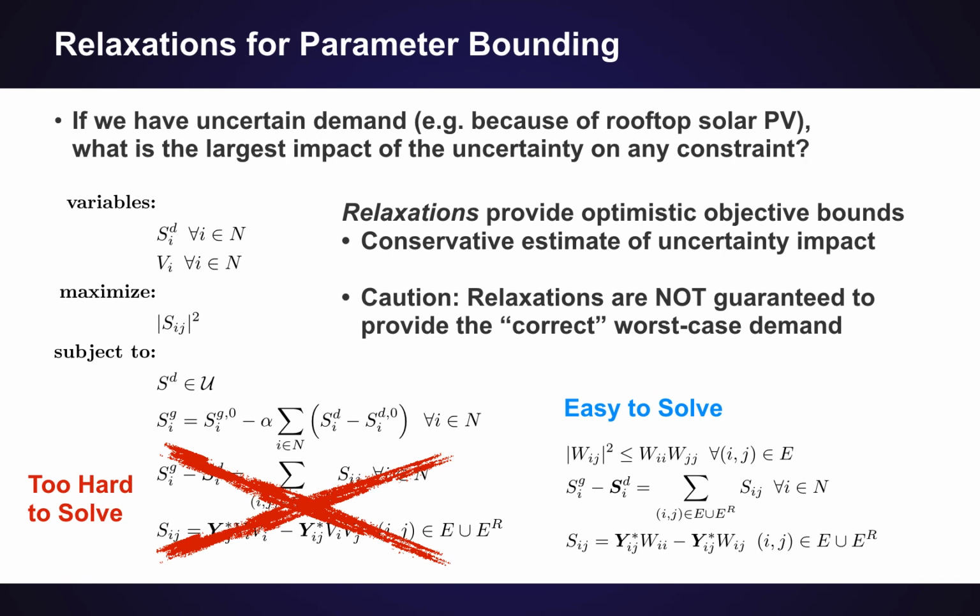Also one thing I would like to note when we are looking at this problem is that here is one good example of a case where we are changing the objective in a way that could make the relaxation become less tight, giving us less good bounds on the objective, because here we are really trying to maximize the power flow on a line. And if you have been following all of those videos we have had here, you have seen several times that one of the places where the relaxations are typically able to cheat is that they are able to throw away power on the line.